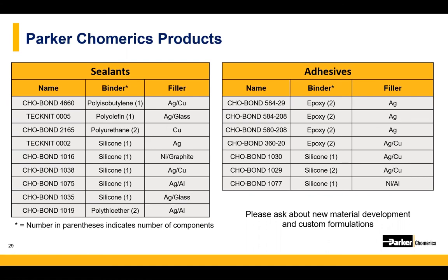Good point. Primers. And I guess building off of that, do we have information about adhesive strength from our conductive compounds to various plastic materials, whether that's a polyethylene, a PVC, things like that? Yeah, so we do have some data over in our applications lab. The problem is that there's so many different types of grades of plastic. Even if you talk about a polypropylene or a polycarbonate material, they have different glass fills and different grades. So it's really very specific to that particular grade of plastic.